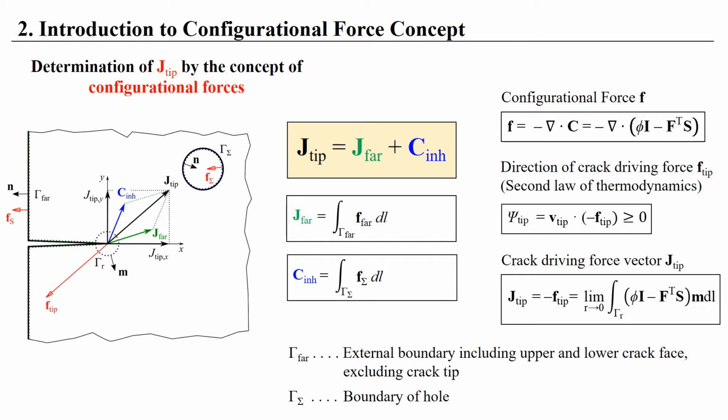The configurational force is based on the work of Eshelby and describes a thermodynamical driving force on a defect. The configurational force F is defined as the divergence of the energy-momentum tensor C. As we consider a crack to be a defect within a material, the configurational force F tip at the crack tip can be considered as physical crack driving force.